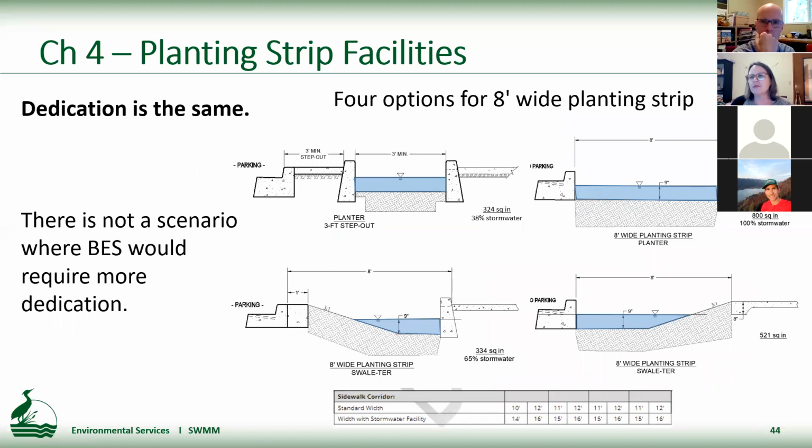However, the idea is not to make more swales or to require more right-of-way dedication. The intention is to encourage other design solutions in that 8-foot wide planting strip.